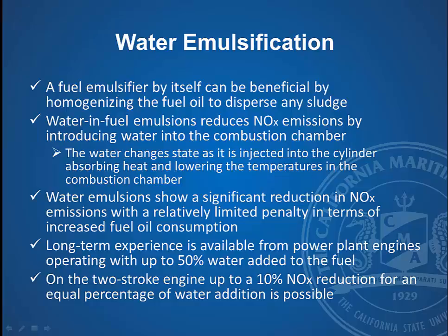So it is sizable. Long-term experience is available from power plant engines operating with up to 50% water added to the fuel. Again, this has been used shoreside, and it is a proven technology. On the two-stroke engine, up to a 10% NOx reduction for an equal percentage of water addition is possible. One of the advantages of this system is you can use it at pretty much any load. So this can be used to, say, lower your NOx emissions as you're coming in and out of port, and it can be easily shut down.